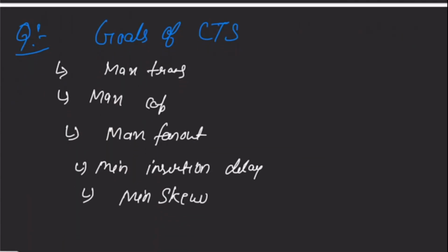Now some CTS related questions. What are the goals of CTS? Our main goal is minimum skew and minimum insertion delay. Next are max transition, maximum capacitance, and maximum fanout. So these are the goals of CTS we need to take care of.